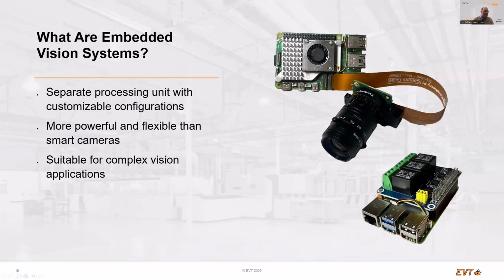So you can use the embedded platforms either with these specialized MIPI cameras, which might be really interesting if the camera is in the same housing and you don't need, for example, a very high-speed trigger interface, then the MIPI camera is a really good option. In all other cases, you have the option to use any of the GigE or USB cameras to connect it to the hardware and capture the images for the machine vision solution.